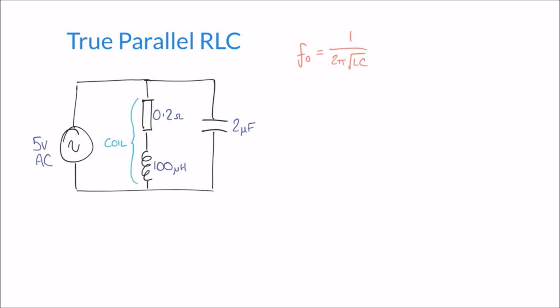And the formula looks like this. f0, again because it's for resonant frequency, is equal to 1 over 2 pi multiplied by the square root of 1 over LC minus R squared over L squared, and that whole lot is under our square root. So it's a slightly more complicated formula, but we're going to use it, even though our resistance is negligible. We'll also see what we get from our original formula. In our case, the results are probably not going to be much different because that resistance is so small. So let's start by using our second formula, and we can put some values in.